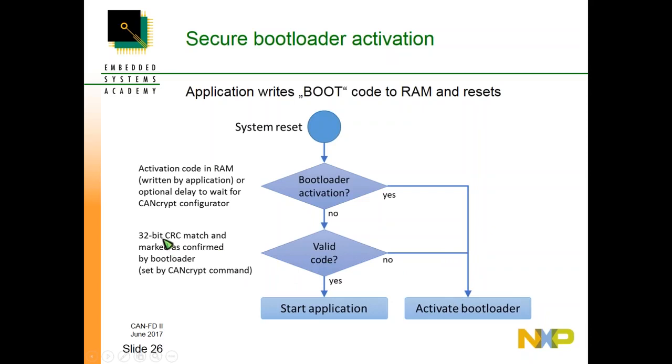On this lower level, by the way, we only use a regular 32-bit CRC, because at this point the application is already unpacked and flashed into the device. So the complex decrypting and authentication only happens the first time the software is installed. Once it is installed, just the 32-bit CRC checksum is used.